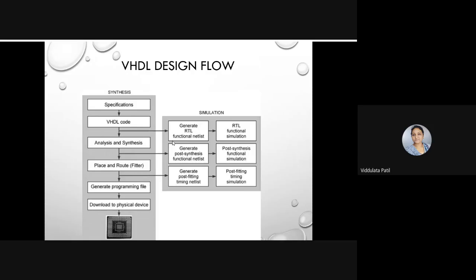Once we get those connections, after synthesis also, we are placing and routing those components in such a way that they will fit in a small space, and it will reduce delays and many parameters related to this design. Then after that we are generating a post fitting timing netlist, and post fitting timing simulation is also done.